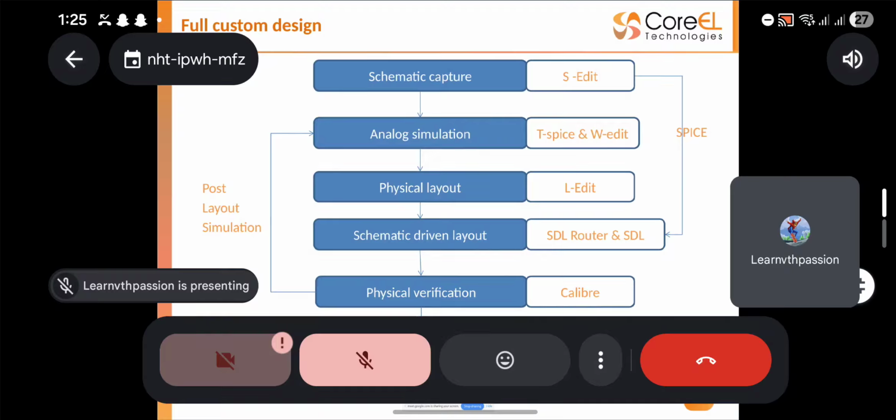And again, in the analog simulation, you can use different simulators: ELDO, AFS, and TSpice. We will concentrate on TSpice for the academic purpose. If you have some complex design, for example, for an inverter and these circuits TSpice is more than enough. If you're going for some common source amplifier, some op-amp, operational amplifier, or if you are planning to design some static RAM, then you can move with ELDO. AFS is not necessary, I guess, because it's a complete industry level. Whenever they're running some industry-oriented things, it will be useful.